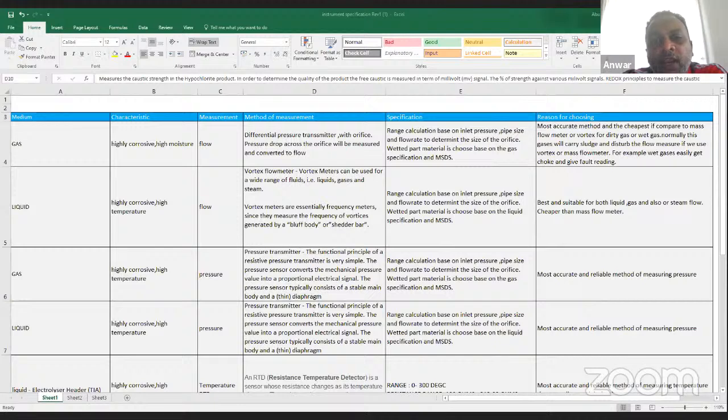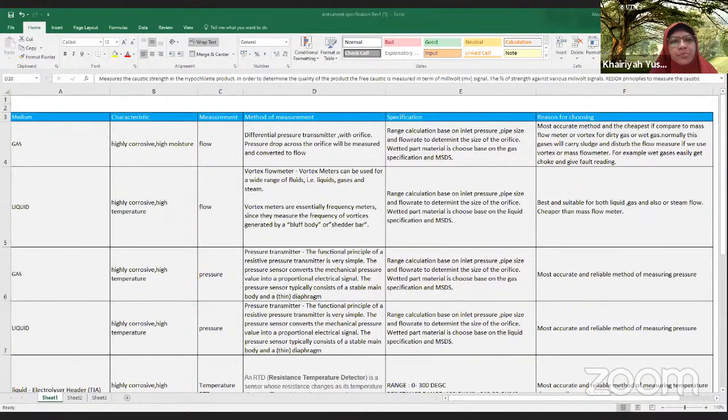From the ultrasound signal, you measure the gap between the liquid in the tank and the available space in the tank. This instrument is not in contact with the liquid itself. But if it is a noisy process and the level is choppy, it will be problematic. There will be some interference.